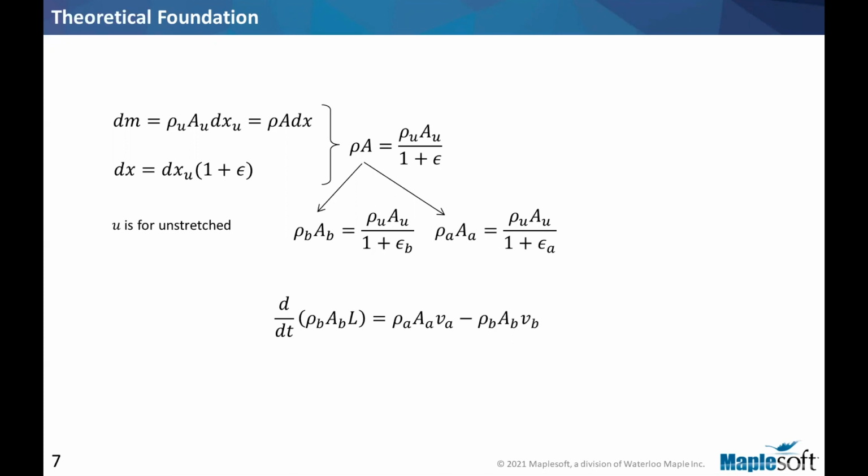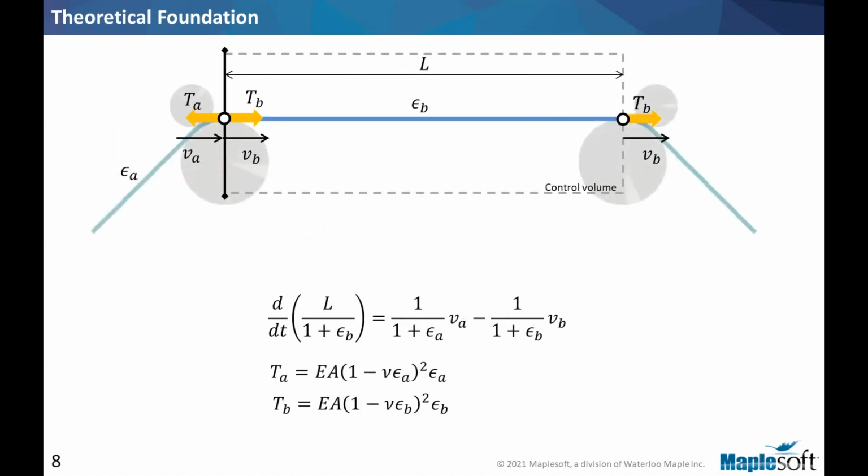So we can simplify that and get to this simple equation as a result, which is the basic, fundamental equation describing the velocity, tension, and deformation of the web. In a lot of work, they go further at this point and linearize this. We don't need to. We'll let MapleSim deal with this nonlinear equation, as it does very efficiently. The two other equations there are the tension-strain relationship.